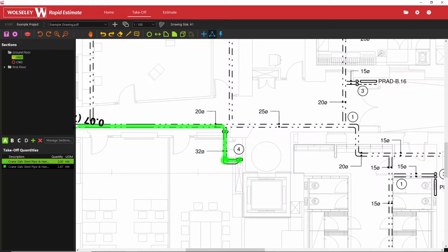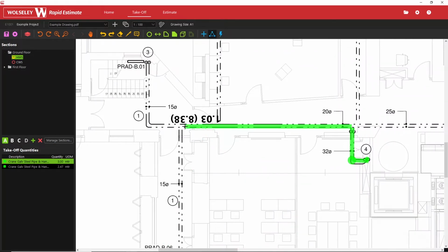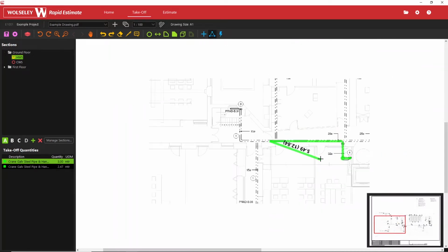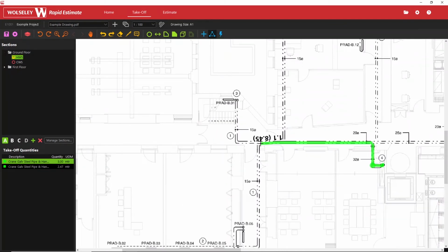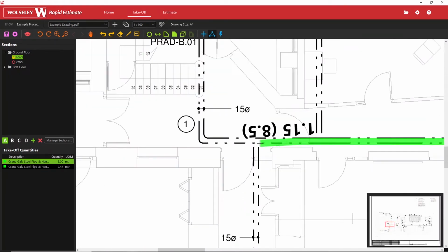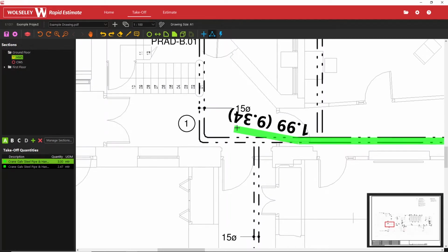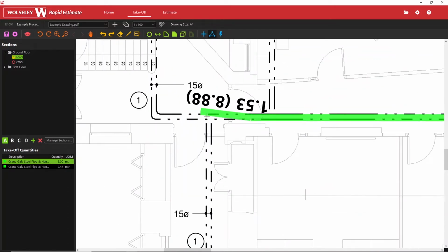Now, this is to do with a little bit of control and moving around on the software. So you've got two options to carry on, well, three options in a sense. You can either use your slide bar down here and carefully select it and drag yourself along to exactly where you need it to be. Alternatively, you could have zoomed out and then use the wheel and your pointer to select where you would like to zoom to and roll the mouse wheel towards the monitor to move in there. Or what I would personally recommend to move around easier on the drawing is to push and hold the mouse wheel down if you do have one, which should then end up looking like this. So now you can safely drag yourself around the drawing, like a panning tool, to move exactly where you would like to be.